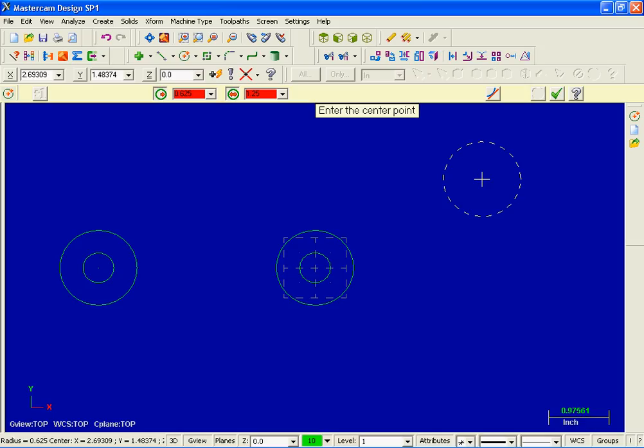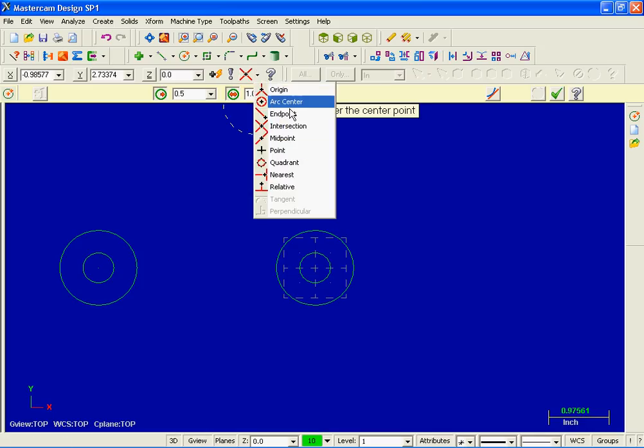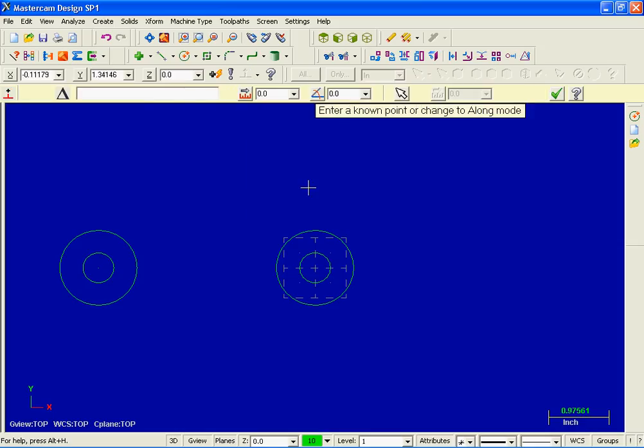The next thing I'm going to do is create the 1/2 inch radius circle up on the top. So let's go up, and in the radius section I'm going to click on this icon to deactivate the locking feature, and in the white space for radius I'm going to input 1/2 and then hit enter. 0.5. Now for the center point of this circle, we're going to use polar coordinates. So when prompted for the center point, I'm going to move up to the Order Cursor ribbon bar, open up this drop down, and right at the very bottom we've got Relative. I'm going to click on Relative.